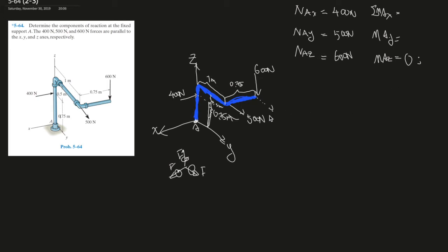That's wonderful. What's really nice is that with 2 unknowns and 2 axes of moments that we can draw, when you have x number of unknowns with x number of equations containing those unknowns, you're guaranteed to find the unknowns using matrix or substitution, whatever you're comfortable with, right? So to start, let's say the moment about the x-axis at A. Sorry, I wrote those backwards, but you get the idea. At A, the x-axis. So 400 obviously won't do anything because it's parallel to the x-axis.